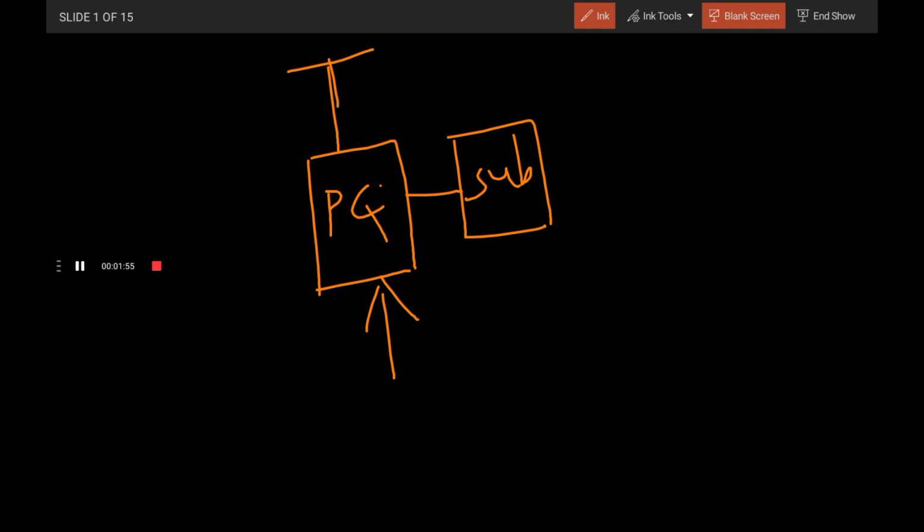In the power gating concept, the basic agenda is that whatever voltage you supply to the subsystem, you do not provide the power rail or direct supply to the subsystem without turning on the corresponding subsystem. That means without settling the corresponding subsystem condition, you are not applying any supply voltage to the subsystem. Obviously a question arises in every student's mind: sir, what happens if you apply the power supply without enabling the corresponding device to the complete static mode?